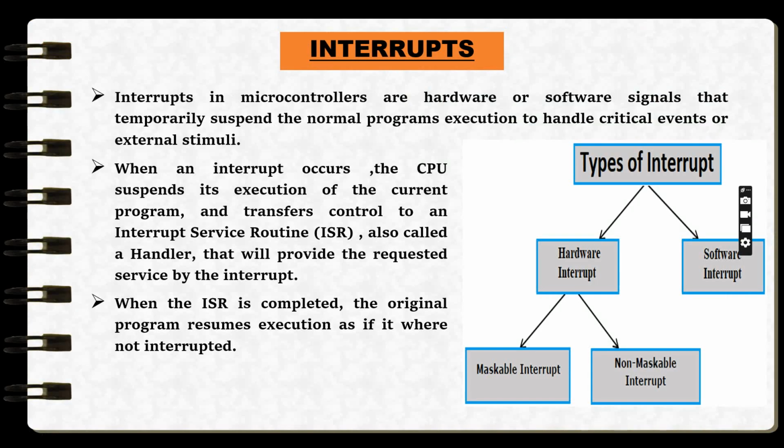Now let us look into the interrupts. Interrupts are nothing but microcontroller hardware or software signals that temporarily suspend the normal program's execution to handle critical events or external stimuli. When an interrupt occurs, the CPU suspends its execution of the current program and transfers the control to an interrupt service routine, which is also known as the handler, that will provide the service requested by the interrupt. When the ISR is completed, the original program resumes execution as if it were not interrupted.